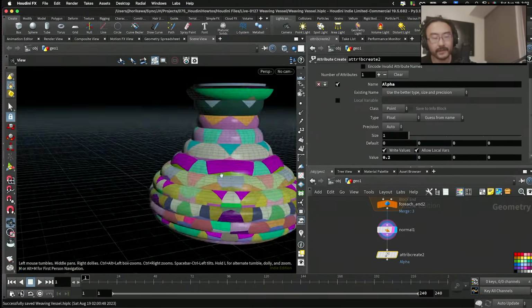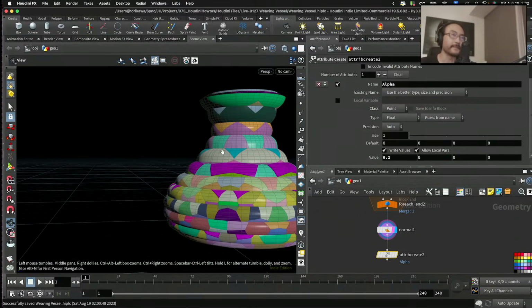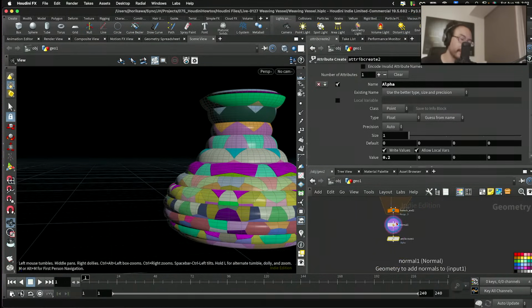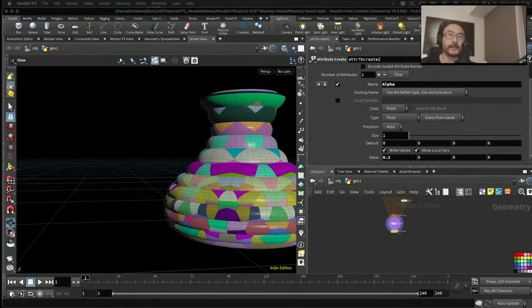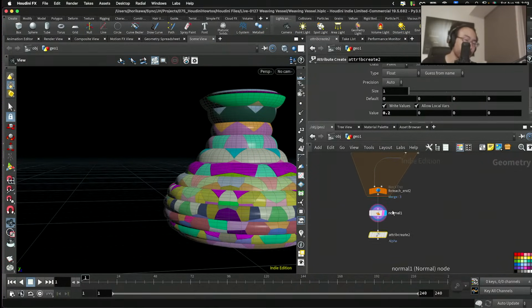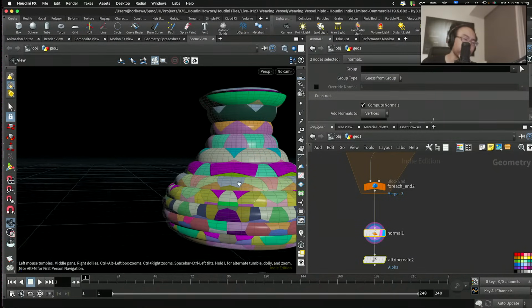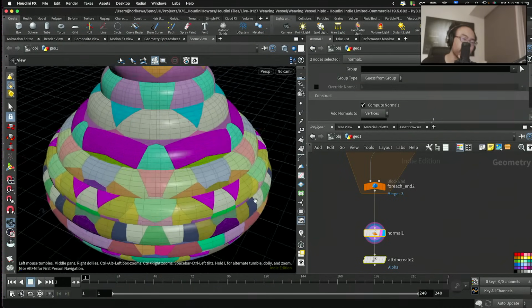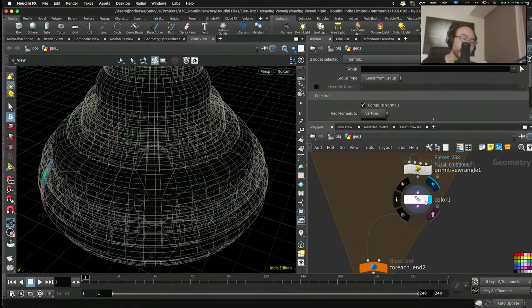Alright, so now that I have this profile surface, what I'm going to do next is to get the outline curve for each voronoi and then try to create a weaving pattern out of these. Okay. So let's do that. And where shall we do that? We could do this outside the loop or inside the loop in order to get the curve. Which way is better? It's fail-safe to just do it inside the loop, but it's going to be slower. It might not be good to do this outside the loop because there's a chance that some of the points are touching each other for different layers. So let's just do this inside the loop.